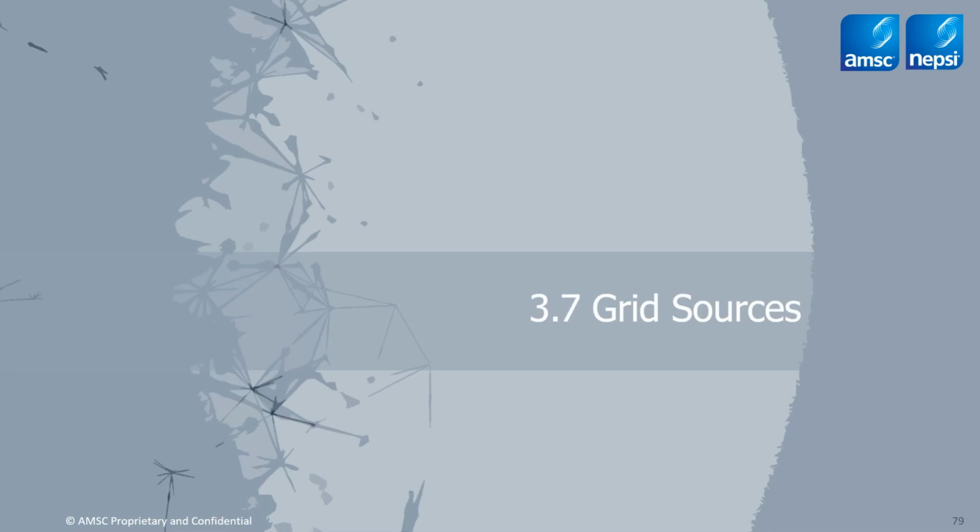Are L and C constant against frequency? Yes. And in fact, that is exactly the definition of the linear network. That is exactly what we're talking about. Those constants, L and C, not changing as frequency is going up or down. Yes, that is exactly true. That's what we're trying to simulate. And that's what we are actually assuming for all AC network analysis, that they're constant.